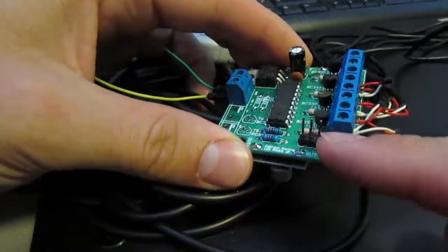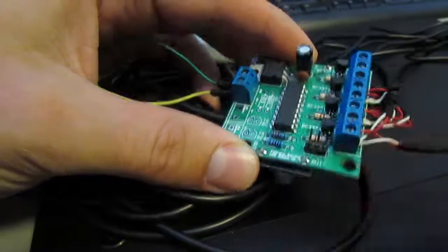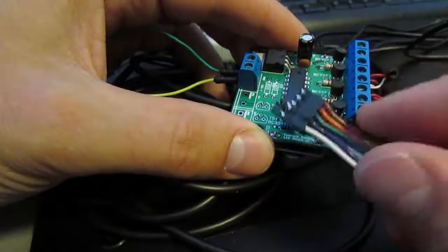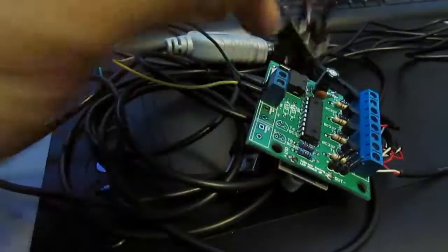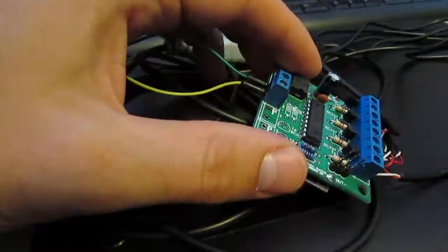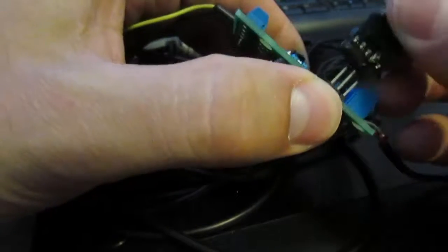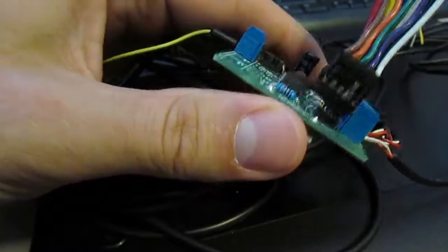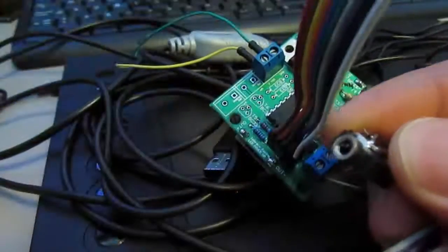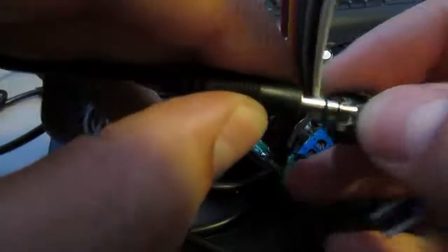So if you remember in the board design, I put 3 header pins on the board. So one of them will be serial in, serial out, and then a ground. And I just took an old ribbon cable and I pretty much just cut up the other side, and I put my own headphone jack just to connect to 3 of the wires on this side. And so obviously make sure you have them in the right place, and you can just slide your connection from the ribbon cable onto your 3 header pins, and that gives you a programming circuit. And so on this end here, the other end of the ribbon cable, I can go ahead and attach that.